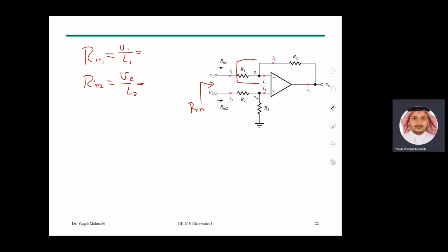And I think you can see it. Rn2 is clear. What is Rn2? The one seen from here, right? Which is the summation of two resistors, which is 110. Okay, right? How about the Rn1? How much is that? If someone can calculate it quickly. This is 5 volts over 0.2273 milliamps.